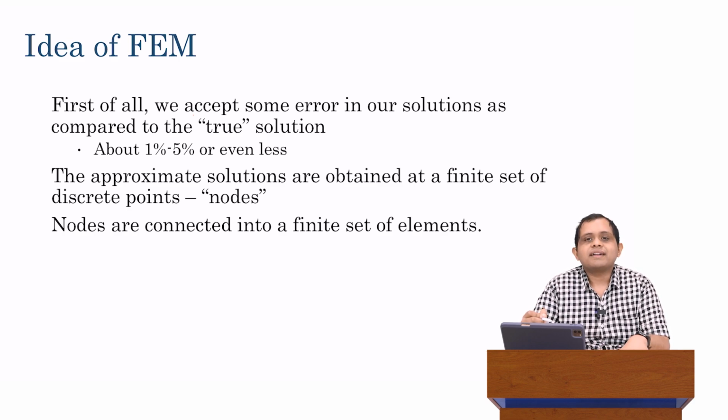If the assumptions are correct, that is, if the slab is very large, if you have continuous support from this subgrade, etc. If all of these assumptions are correct, then we know for sure that our analytical solution is correct. The differences between analytical solutions are the assumptions they make about maybe the type of loading or whether you include shear or not, but it's not the correctness of the solution. As long as you agree with the assumptions of the method, the solution carries no error at all. But the first thing we have to understand is, in engineering, we really don't care about solutions having 100% accuracy. The real reason for that is, in engineering, nothing is 100% accurate.